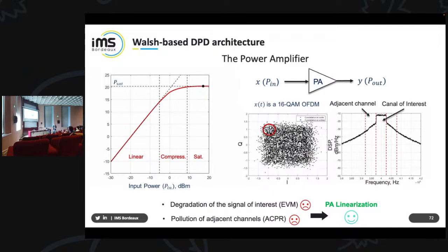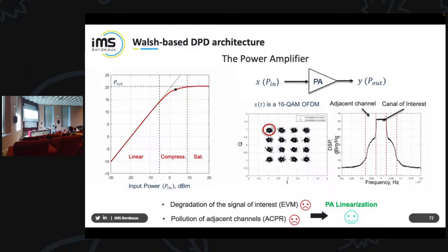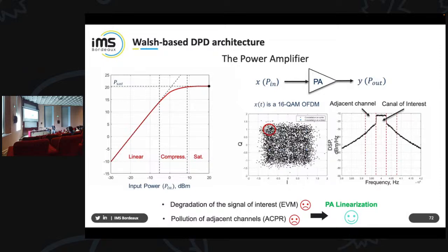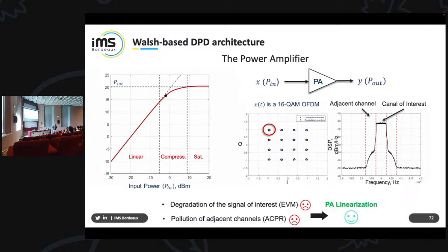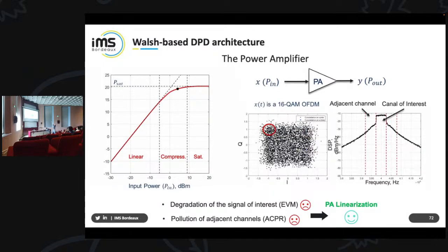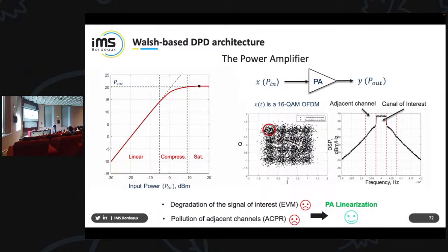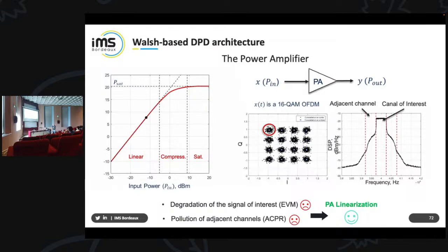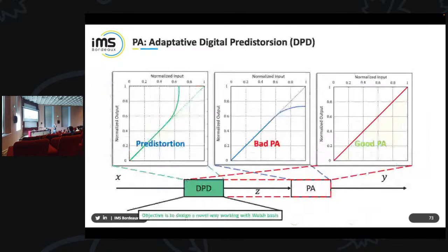And if your circuit is not properly designed, see, this is what you have on the right. The right is how your signal is modulated with the dots. It's 0 and 1. Then it's a cloud. You cannot recognize what is 0 and 1. And the spectrum you have there on the completely right, it's okay at the beginning, but then you have shoulders. The higher you go in frequency, you're going to pollute the other channels. So you will measure that Friday morning, and you will see how we can compensate that. The answer is to linearize.